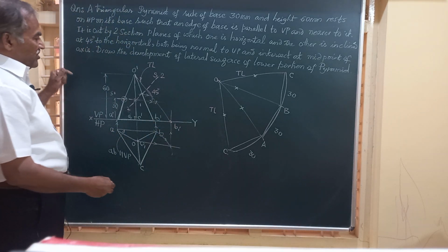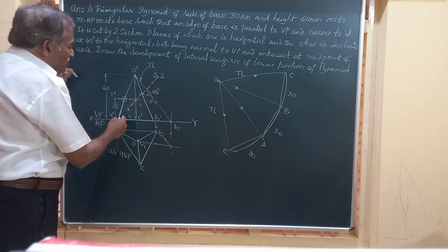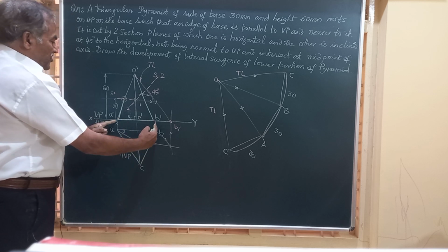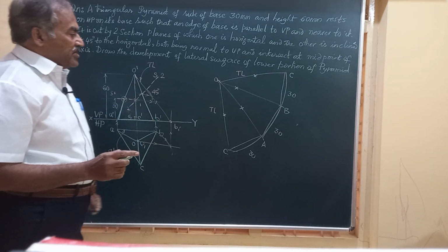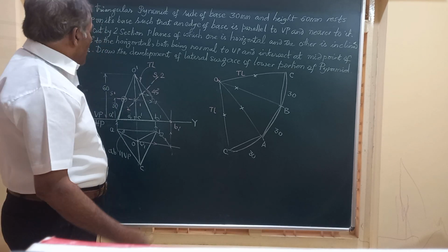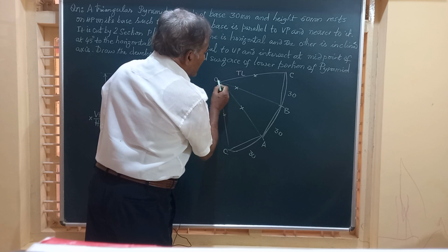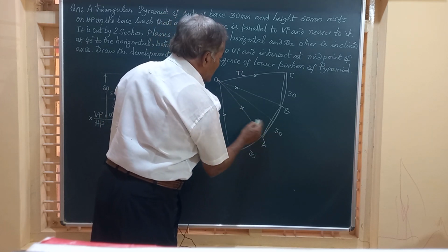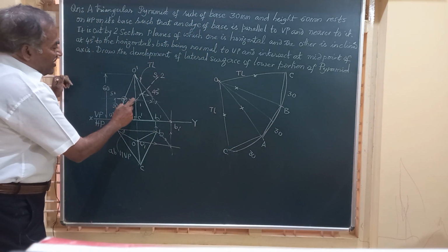But what has happened here? These section planes S1 and S2 intersect at the midpoint of this AB, the edge AB. You can just observe here, exact at the midpoint, they are intersecting. So we have to get a point for that also. How to get that, friend? So friend, here, you got AB here, you mark the center and draw a thin construction line through that.